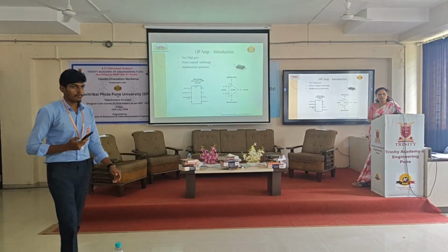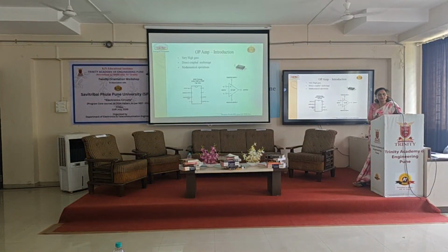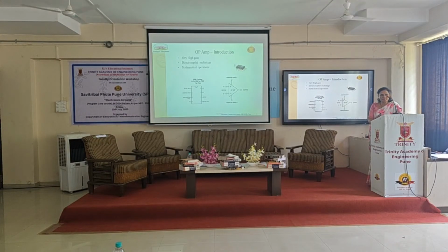Before going into detail on the operational amplifier, we have to mention its features. It is a very high gain amplifier. It belongs to the direct coupled multi-stage family, and it is used to perform different mathematical operations, from very basic addition and subtraction up to log and anti-log. Now, the IC has 8 pins along with the symbols.